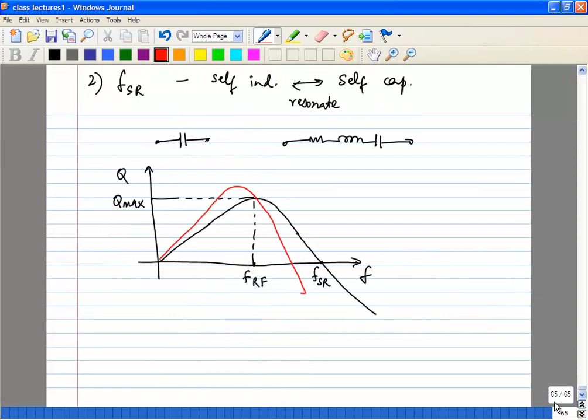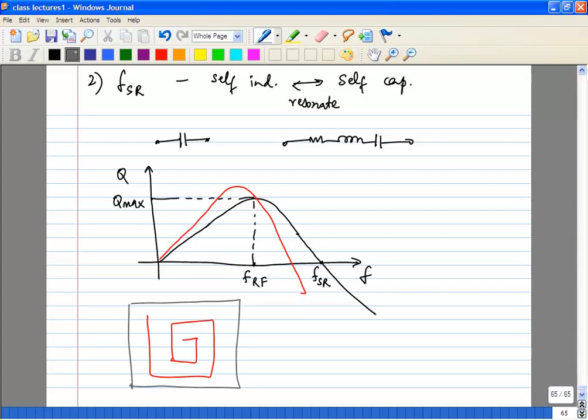So let's say we have an inductor, okay. Now what we're going to do is we're going to put a ground shield, okay. Now you will still have some eddy current flowing through the ground shield, but because of the low resistivity, I square R losses will be lower, okay. So let's assume that is the case for now. Next we'll look at what happens if that is not the case.